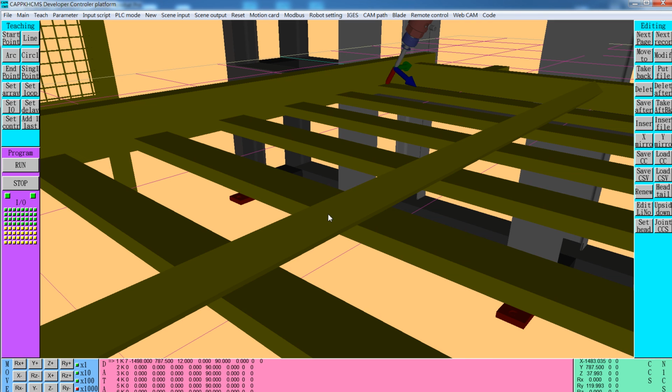This is the coordinate we want to lock for the instruction 1. We remove the K7 first by pressing renew, and then change the coordinates to joint mode, and lock the first points, and change to Cartesian again, and press S plus 1, 2, 3 times, and then change to joint mode and lock the second points. The third points will retract back to the first point's positions.